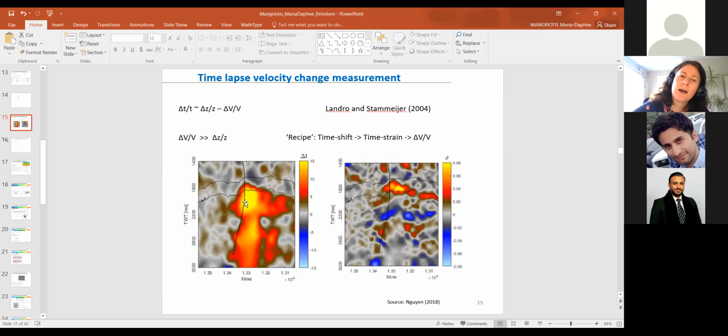So whatever you're measuring down here is affected by what's up there as well. But by taking this differentiation, you're undoing the effect of the top. So essentially you're doing a layer stripping approach to evaluate your velocity changes in a depth step manner.